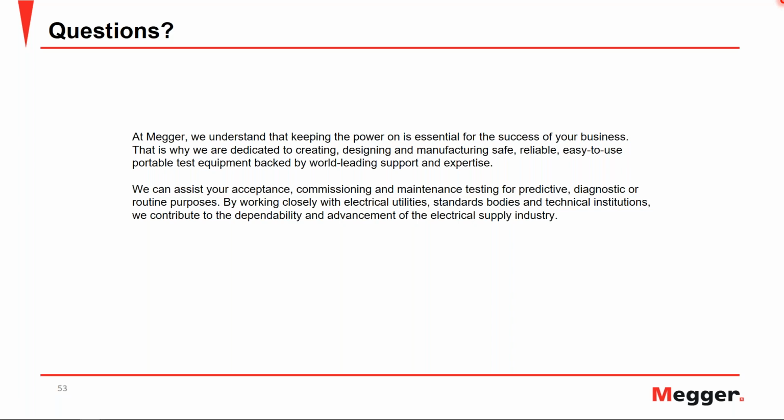So all these come into play, and it's impossible to get a transformer in the same condition to test every time. So rather than having the transformer in the exact same condition every time, you translate the measurement that you received into a 20 degrees C value. That way it improves your ability to trend those results and compare them down the line.